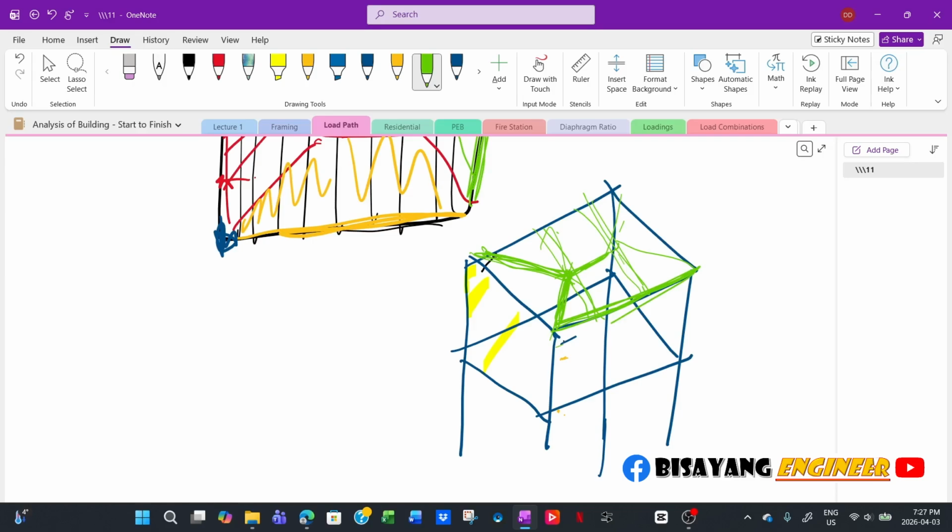So if in your model you apply the load at the nodes only, you are undersizing the beam, because all the loads are supposed to pass through the beam first before going to the column. If you apply it as a joint force right here directly, without passing through your beam, then you are undersizing the beam laterally.